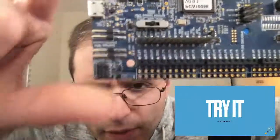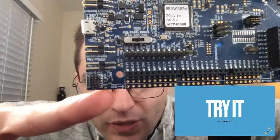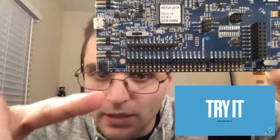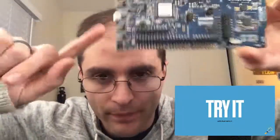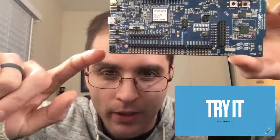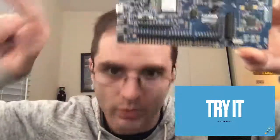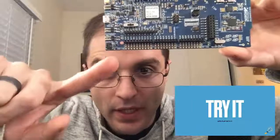There's a jumper right here, and this is probably the jumper. I don't think this board is modified, so it's not bridged. But this is the jumper. It's usually in the same vicinity, though not always in the same place. You bridge that, and you can always check the schematic if you download it from Nordic. You can see which one is hooked up, and it would be the VTarg, and the VTarg will be jumped over to that specific pin, and the 3 volts on the board will be shorted to that once you short it. So that's the guy, and that's the pin.